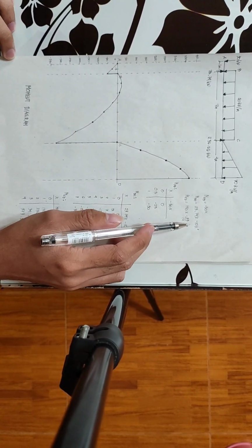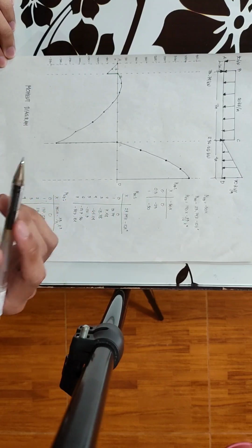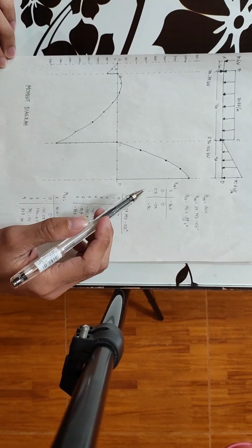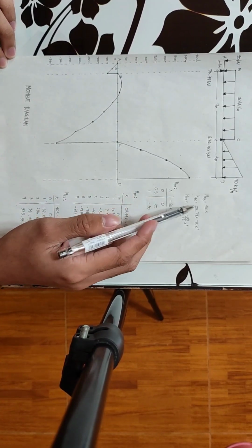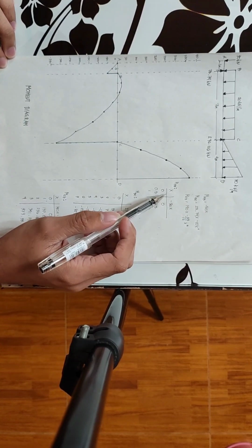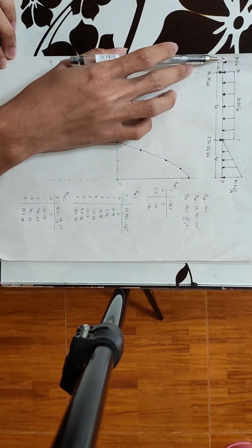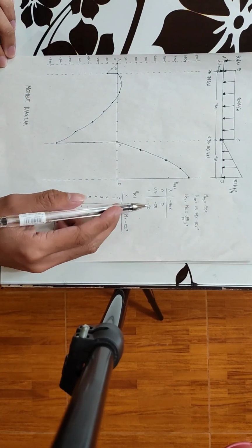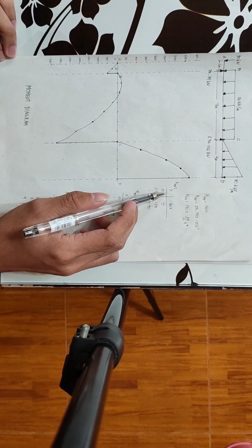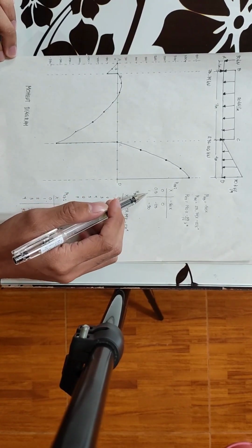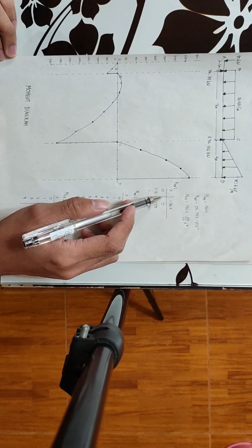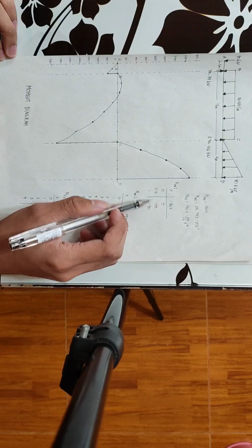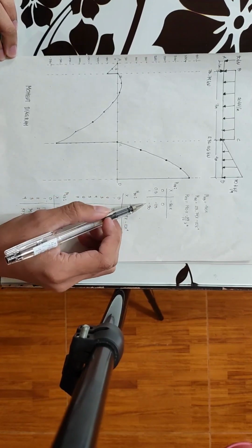So what we're going to do here is the same as what we did in the shear diagram. Since MAB is negative 50x, and from A to B has a distance of 1 meter, we let x be 0 to 1. So if x is 0, it is also 0. Then if x is 0.5, it's negative 25. Then x is 1, it's negative 50.